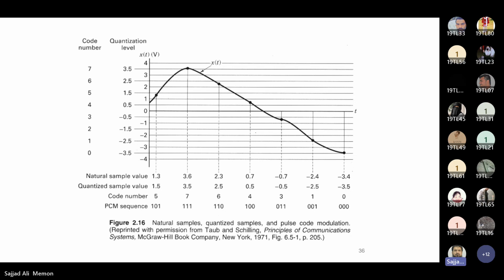But by increasing the quantization levels, we are also increasing the number of bits required to transmit the same information. So we need more bits to transmit the same information as we do with fewer quantization levels. There is a trade-off. Lower number of bits, but higher quantization error.